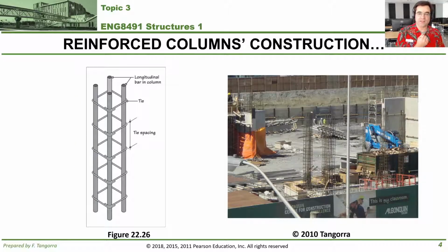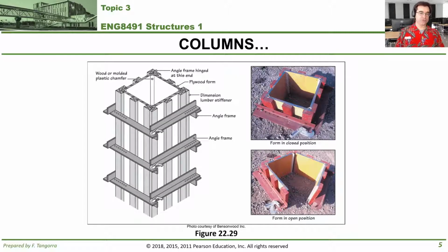So once you've created the reinforcing, you place it on site. Kind of like you see here on the right hand side, either you fasten it to the reinforcing of the column below or to a footing and foundation below. Then, as we've learned, because it's concrete, you have to form it.